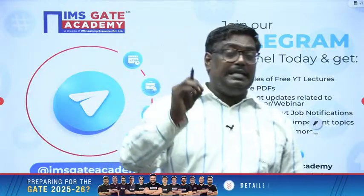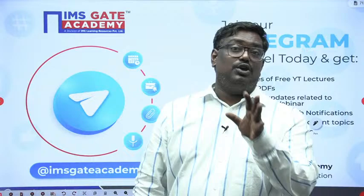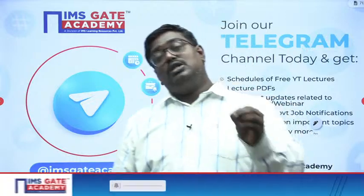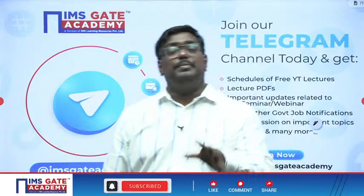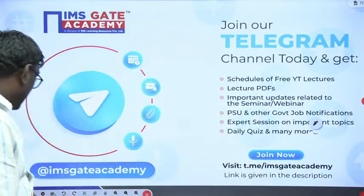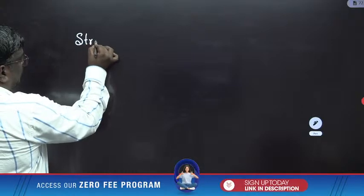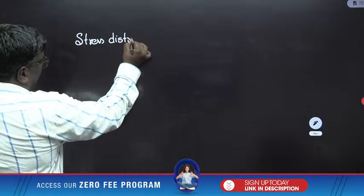It is a condition which is observed only in cohesionless soils. Why quicksand is not observed in cohesive soils is, even though the effective stress is 0, for cohesive soils shear strength will not be 0. This one observation you should 100% observe, sir. And also, my dear students, if you talk about stress distribution, this is another important point which I would like to tell you, sir.